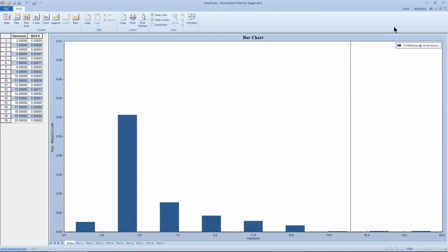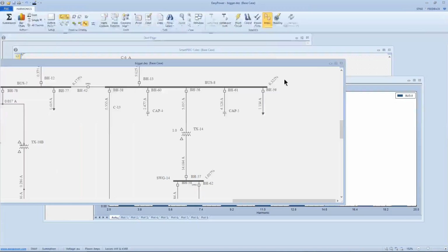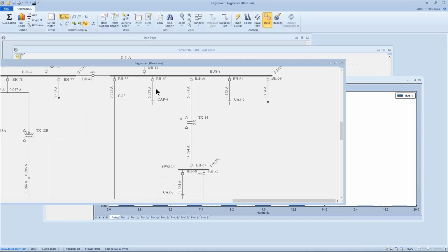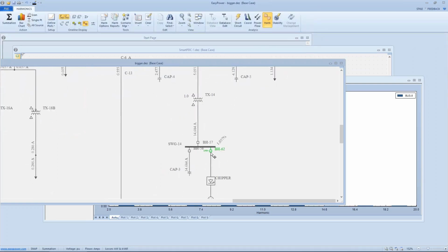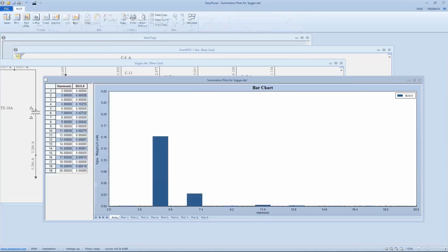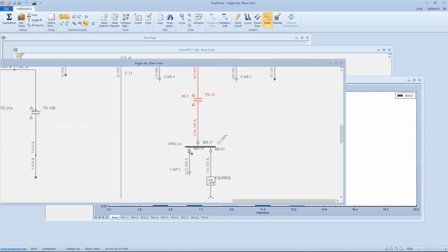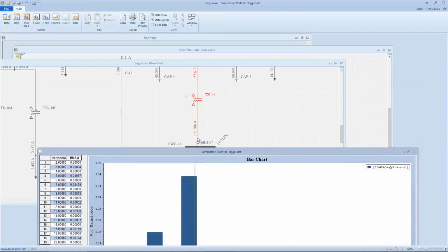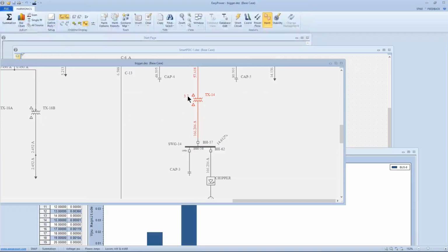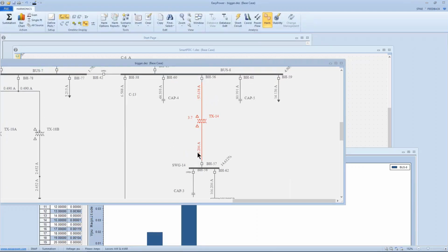If I come back and look at before we went to the VFD, we'll see that effect in other places. So this is something we may want to take into account, especially as we're looking at doing a conversion. Part of that problem, frankly, is that we have the capacitor in the loop, so we have a resonance at that point. If we take the capacitor out, it moves the resonance point and the frequency content in our transformer is reduced, but we still need to be considering derating.